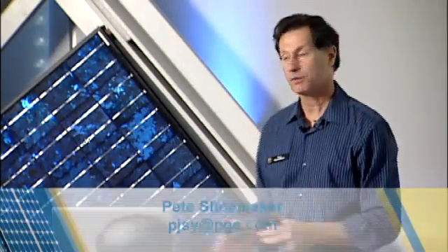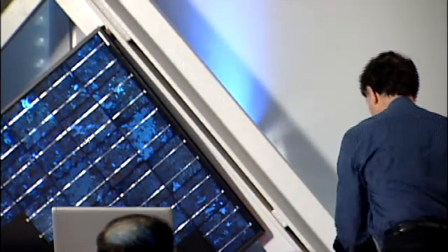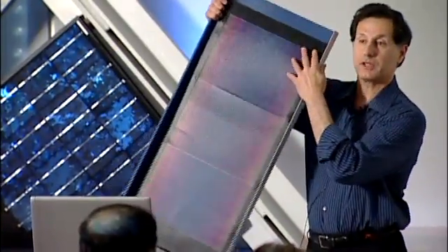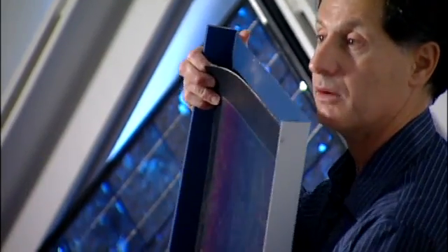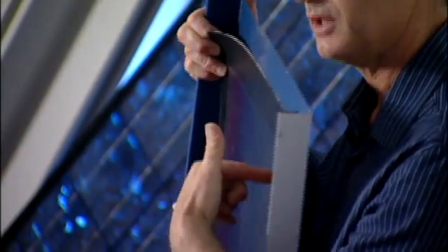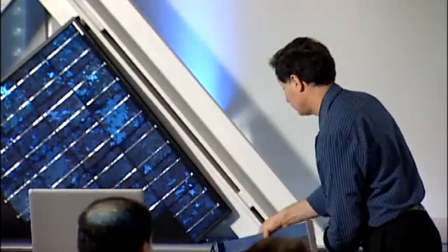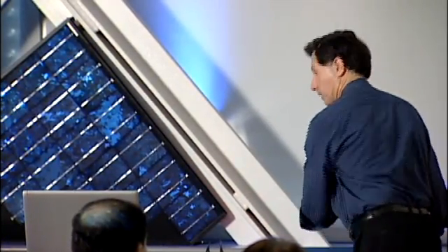The second technology, which is coming on strong now, is called thin film. That's really a whole different technology using a lot less material. It's almost like sprayed or painted on, a different way of producing electricity. This stuff has a lot of potential because it can be used in a lot of different ways. This is a thin film panel right here. One of the innovative ways you can use it is on metal seam roofs. These panels have an adhesive backing, and they can just stick down on the roof without penetrating it. It's a very effective, cheap, and safe installation process.